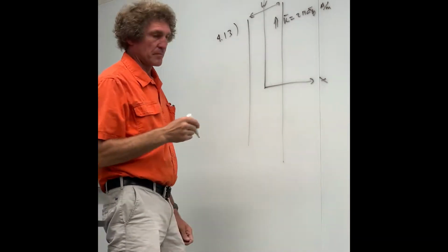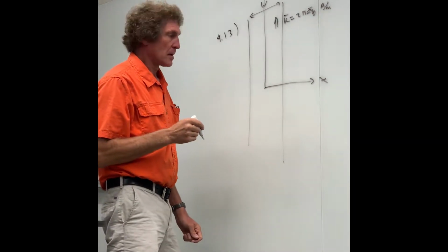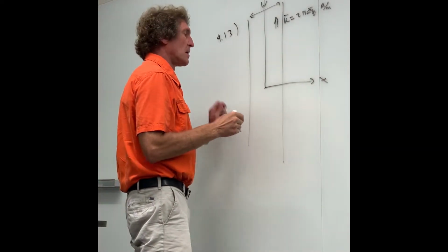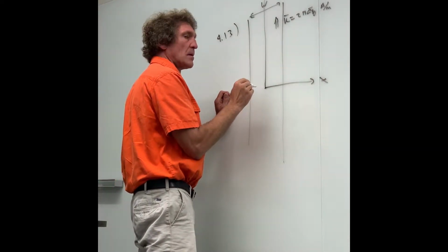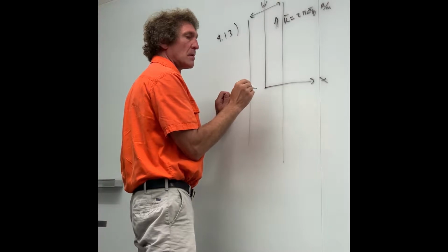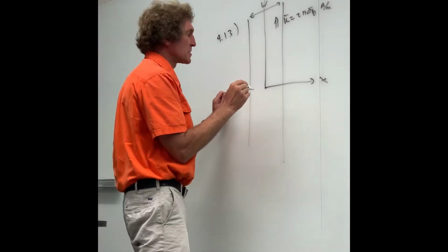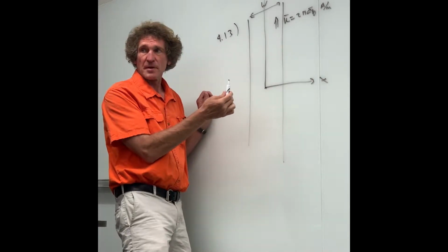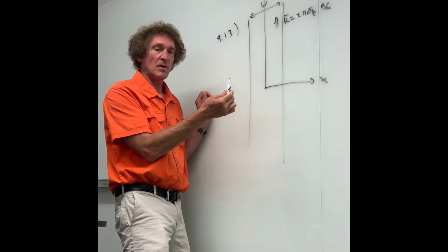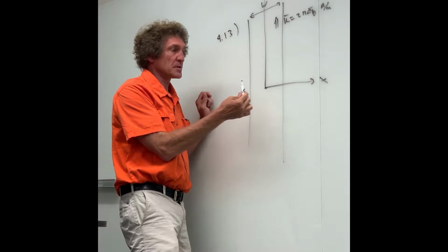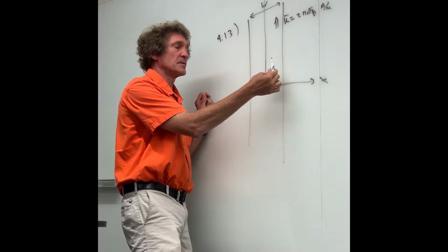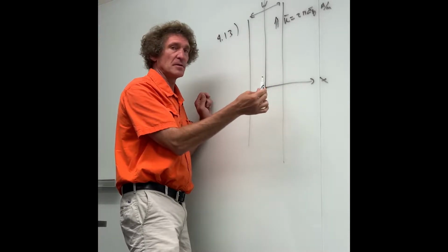Determine the magnetic field intensity at point P, which is (0, 0, 2 centimeters), and then part B, Q, which is (2 centimeters, 2 centimeters, 2 centimeters). So for the first one, they want it right up the z-axis 2 centimeters. And for the second one, they want it at 2, 2, 2. It's going to be 2 here, and that doesn't matter in the y because it's infinite. So it's 2 here, and then 2 here.